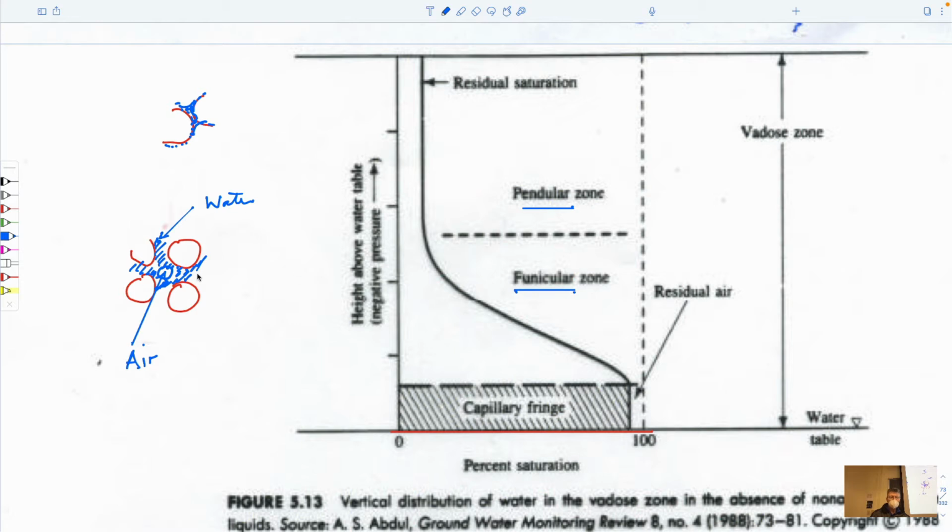And so on average, if you look at the saturations of this REV, the REV would be the volume that includes enough grains that it's representative of the rest of the aquifer. The representative elemental volume, REV, is that each one of these would correspond to whatever is in there. And so the tension saturated zone, almost 100% saturated with water, very little air, perhaps a tiny amount of air left in it because of what we understand about irreducible saturations of air. This would be the minimum amount of water you could have in the system.